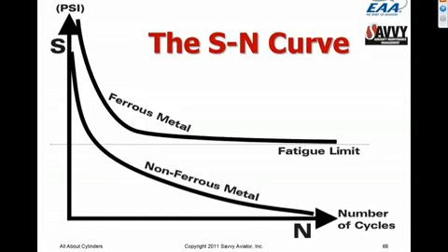They don't typically have an infinite life because eventually they wear out. But in principle, as long as those parts are operated within their design envelope, you can run them forever and they will never develop fatigue fractures. On the other hand, non-ferrous metal like aluminum does not have a fatigue limit. The fatigue limit is 0, which means that no matter how lightly you stress it, after a certain number of cycles, the part will crack.